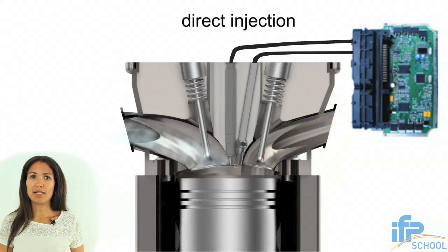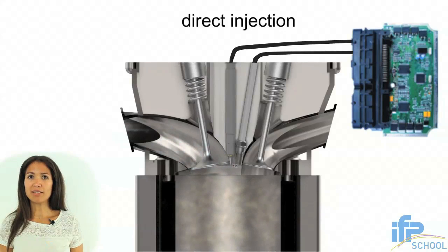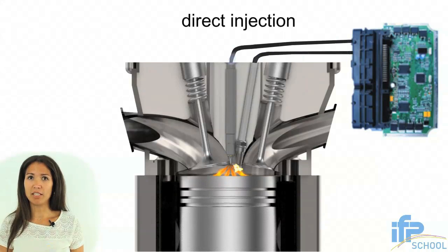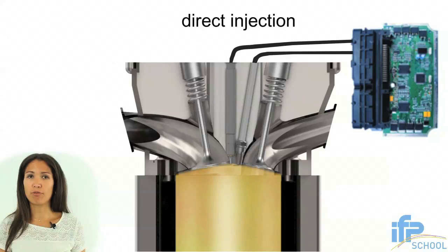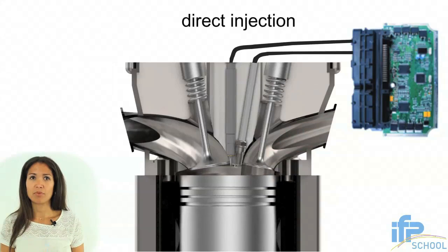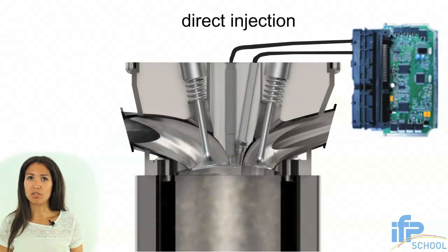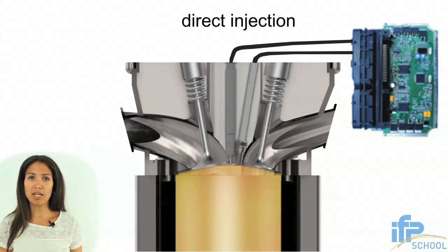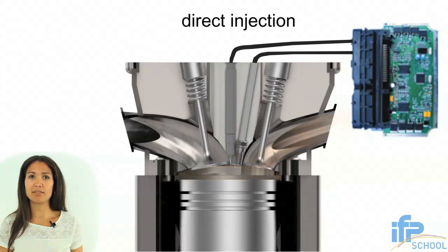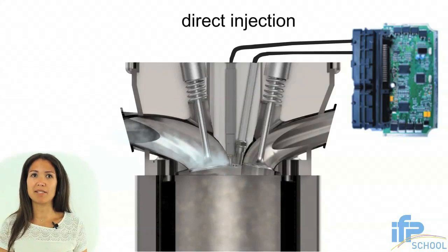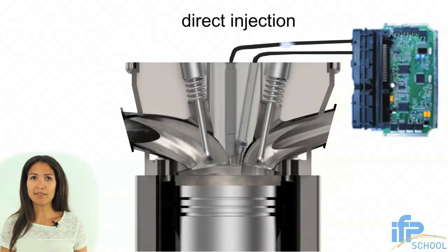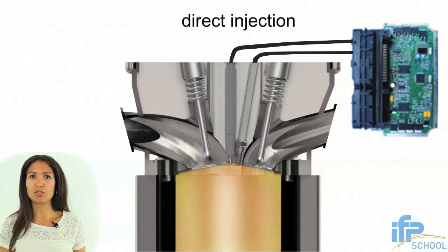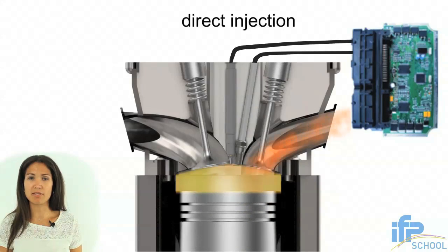Fuel injection is electronically controlled for accurate injection quantity and phasing in order to obtain a correct fuel-air mixture. When the piston approaches top dead center, the spark plug supplies the amount of energy necessary to initiate the combustion of the fuel-air mixture. The spark timing is accurately adjusted to optimize engine performances.